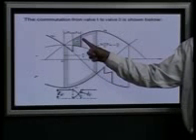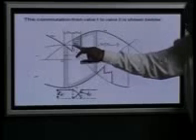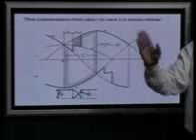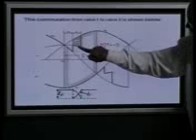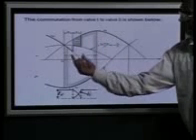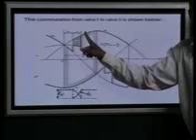We already had, from here to here, the 2 valve conduction without this overlap, and then this area can be subtracted. This area is this minus this from this period, and this is simply alpha plus u. Then you can subtract it and get the DC voltage again, and we will see that in the next lecture.